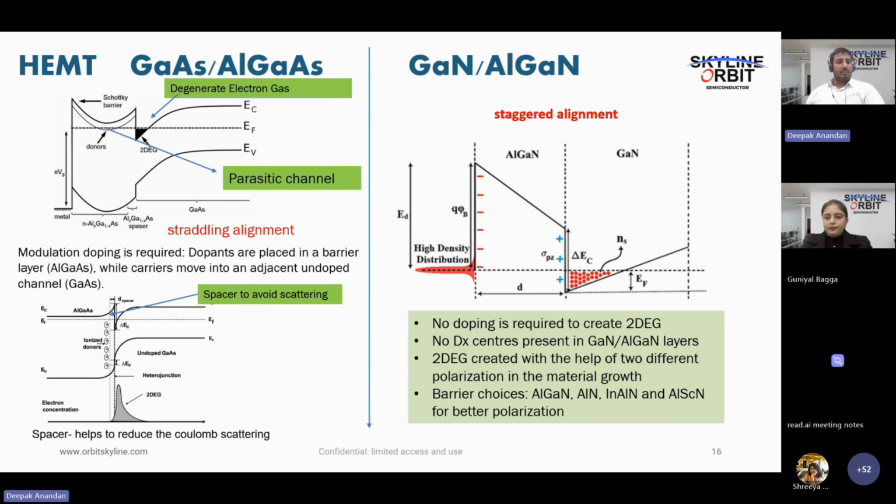So when you have a high band gap material, the electrons which are close to the barrier interface try to jump over to the 2D and form the two-dimensional electron gas. Okay, that's called degenerate gas. The mobility of this two-dimensional gas will be very high. The electrons will not flow in the Z direction. They only flow in the Y and X directions. Okay.